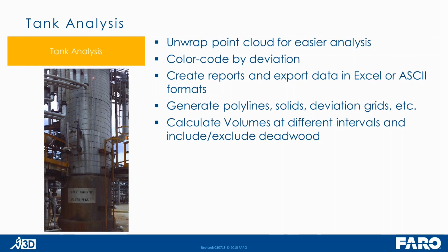Now, in that Excel report, you can do volumes or volumes at specific height intervals, and you can also do around the circumference. So when you bring it into Excel, a lot of our customers are doing, at least in my experience, very short vertical increments and maybe a little bit more lenient horizontal increments. But you can get a deviation analysis on the surface, or a deformation analysis on the surface. You can also get volumetrics at every single height, and it'll give you the specific volume of just that 1/8 inch, for example, and it'll also give you a running total.